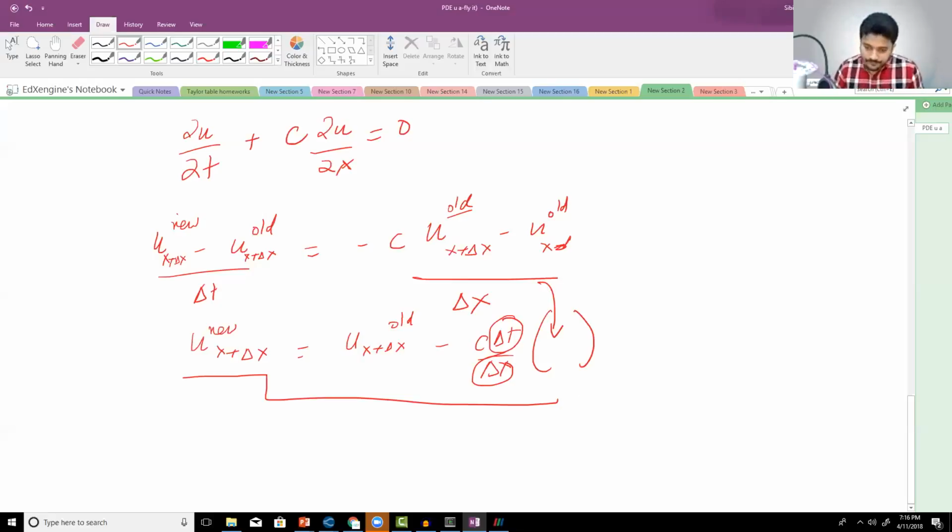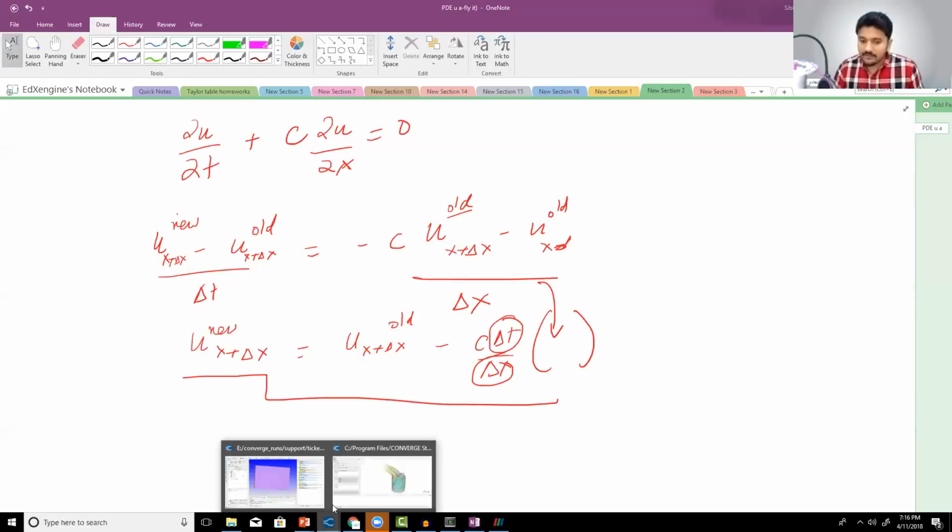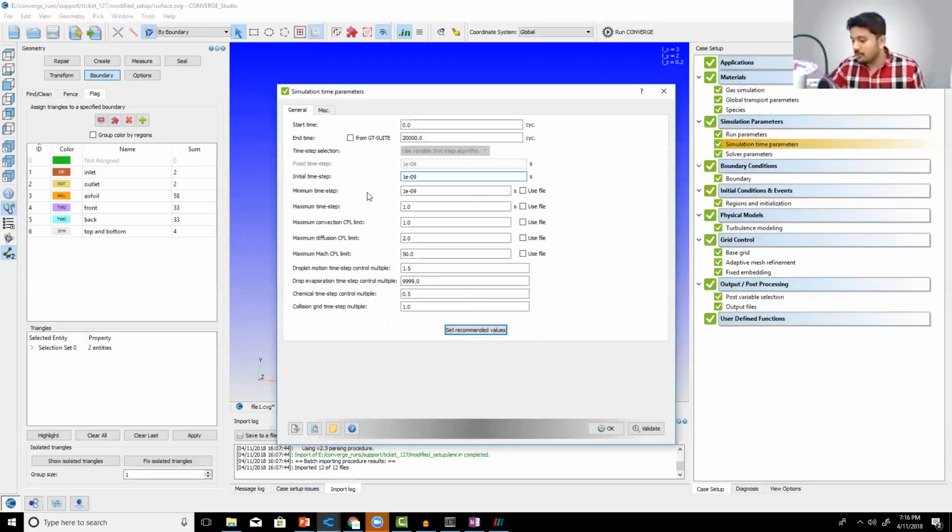That is the problem. So if I go back to the solver, you can see that there are so many parameters like time step, and there are 3 CFL numbers. CFL stands for your Courant numbers. They determine the stability of your system. So we are setting up particular values for those. And these constants are found in any software. It could be ANSYS Fluent or Star CCM, you will find the same constants. Maybe the names would be slightly different.